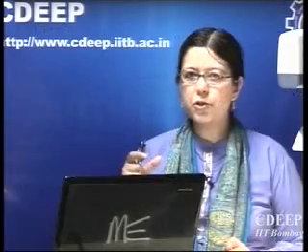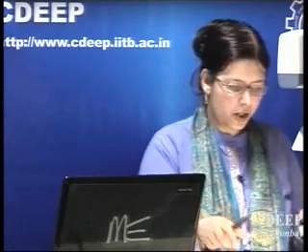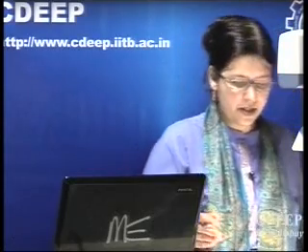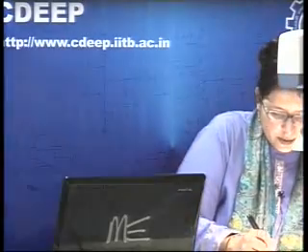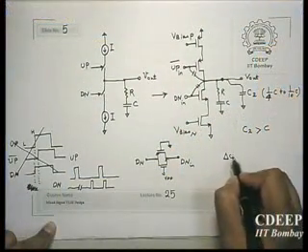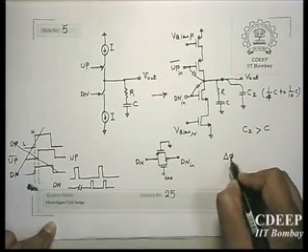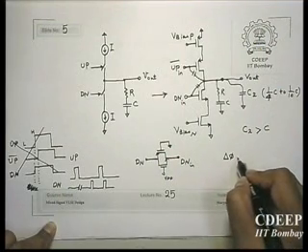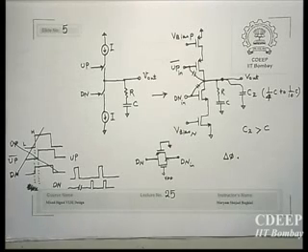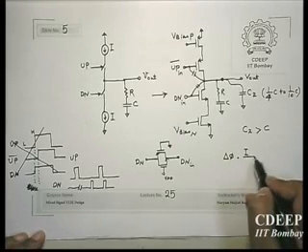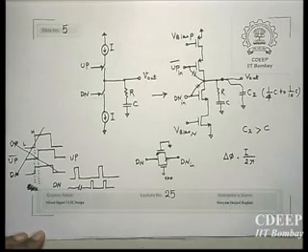In fact, the delta Q which remains will be translated to a phase difference, because we had delta phi as the phase difference, and then you had I upon 2 pi. This was in fact the phase detector transfer function. So exactly that delta Q will be translated to this delta phi.